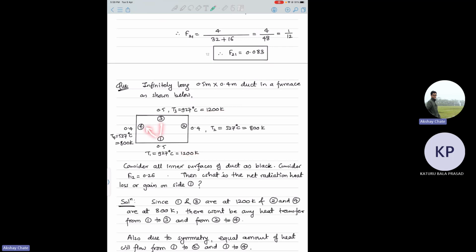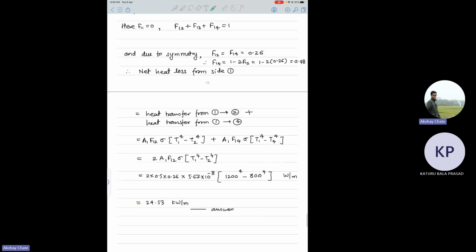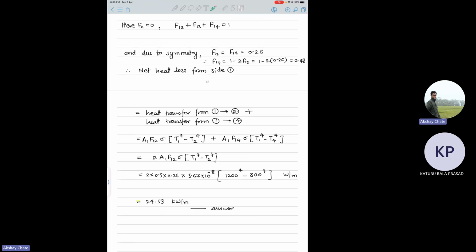This surface is wall number 1. It views 4, 2, 3, all walls. So therefore, the view factor will not be 0.5 in that case. It will be symmetric between 2 and 4, but there will be a non-zero view factor here because view factor is just a geometric property. It is not dependent on the temperature of the body. So I had corrected the explanation, but the video had disconnected by that time, so I could not clarify there. I thought I'll clarify this now.